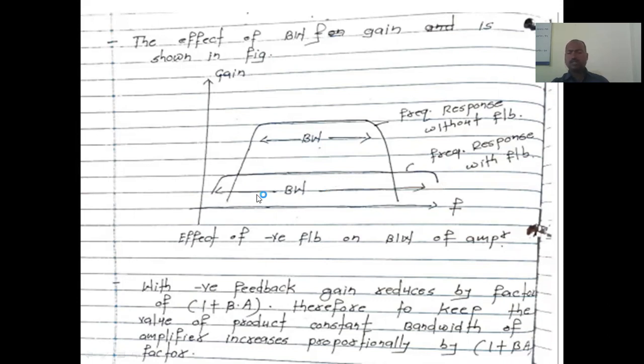The range of frequency over which your amplifier works is called bandwidth. For an audio amplifier, the range of frequency is 0 hertz to 20 kilohertz, or also 20 hertz to 20 kilohertz. So bandwidth means the range up to which your amplifier works; normally it works up to 20 kilohertz frequency. Note that, it is called bandwidth, right?